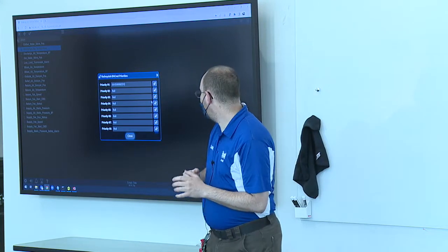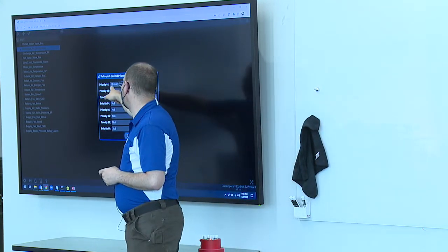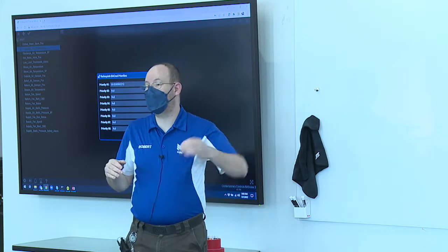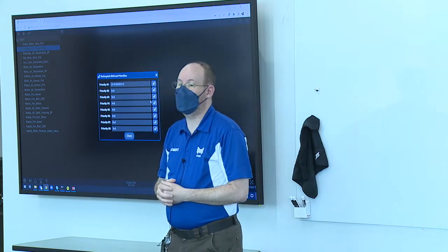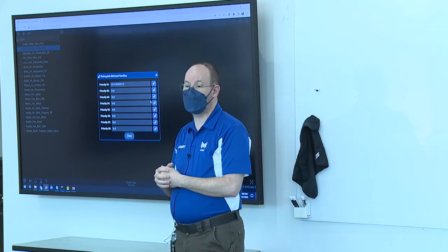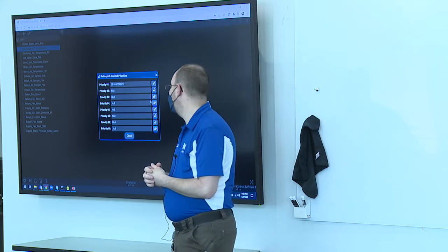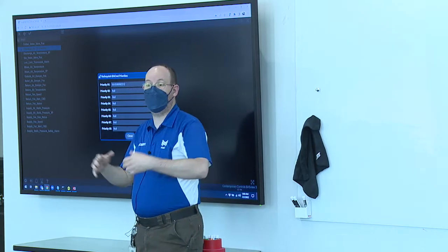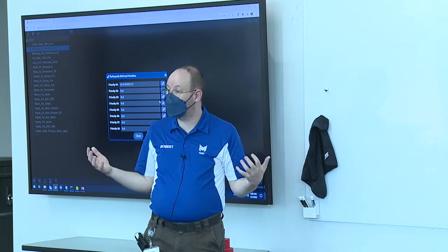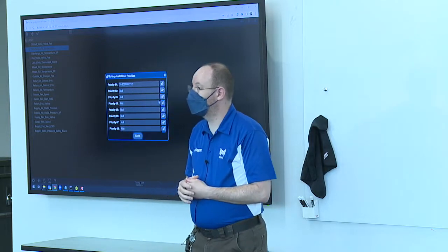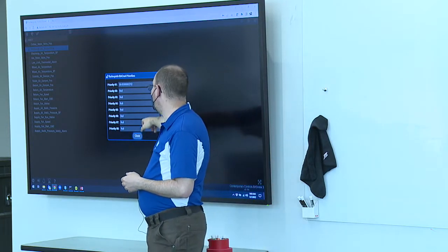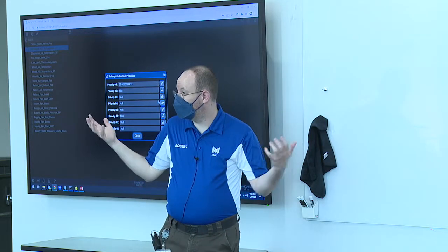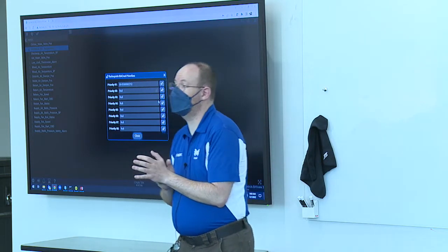So if right now my value is coming in on priority 1, there is nothing higher than priority 1. I cannot override this point. But if it were coming in down at a more normal priority, priority 8 or priority 10 are common ones, then I could write something in any of these priorities above here, and it would overwrite that value.